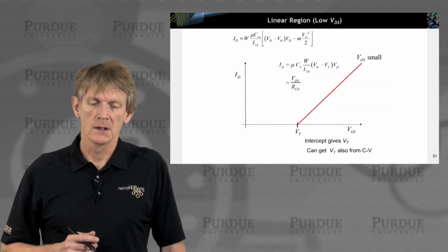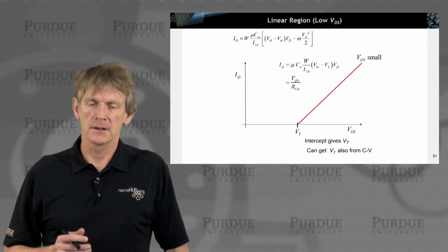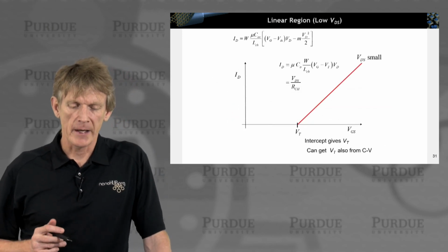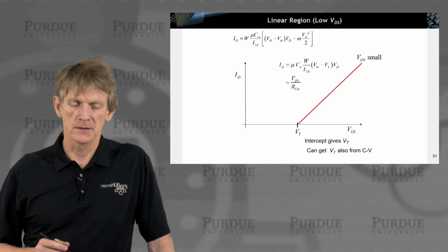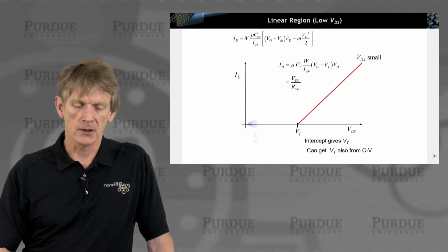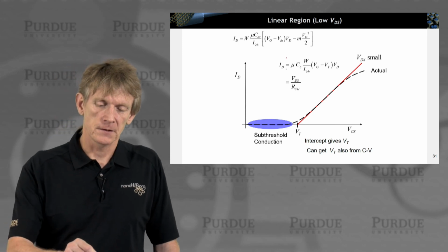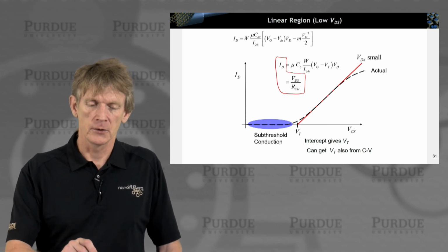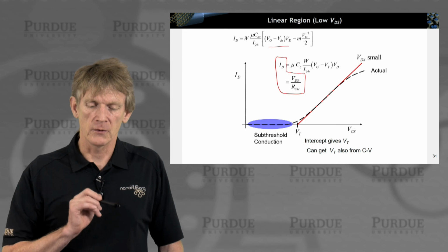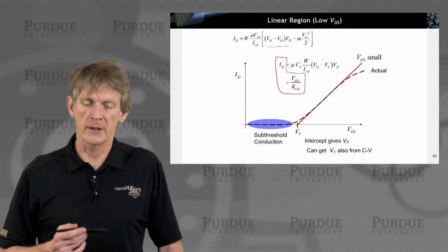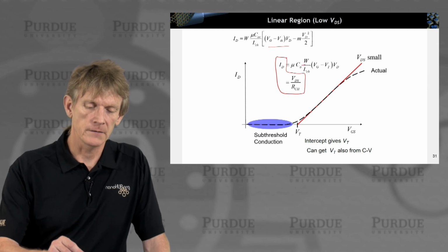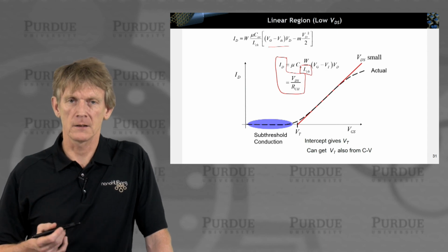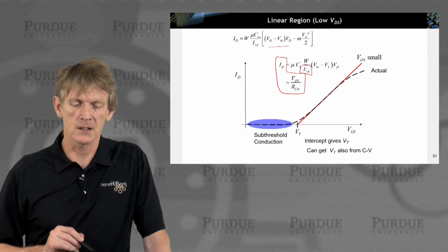Okay, so if we look at the linear region, in the turn-on region here that I had mentioned before, and expand it out there as a function of gate source voltage, you can calculate a series resistance, okay? So here's the expression for the drain voltage. If you look into the linear region, which is just this term, you can derive a channel resistance effectively. That depends on the mobility and it depends on the length of the channel. Okay, kind of makes sense that your channel resistance goes up as the length of a channel.